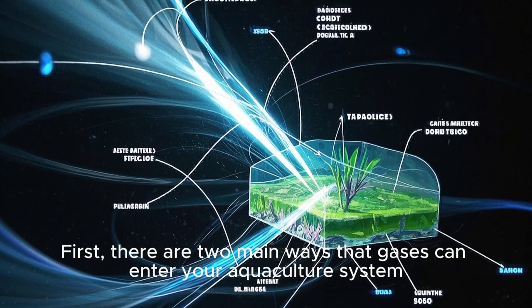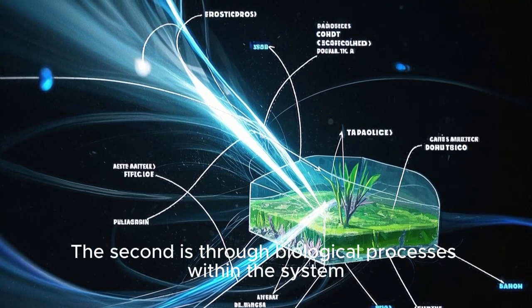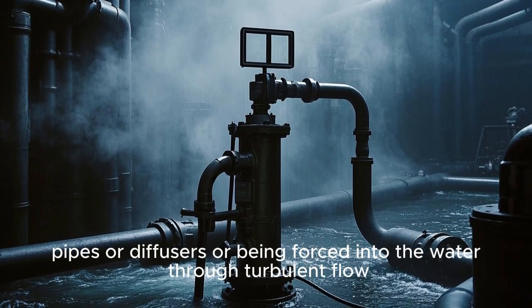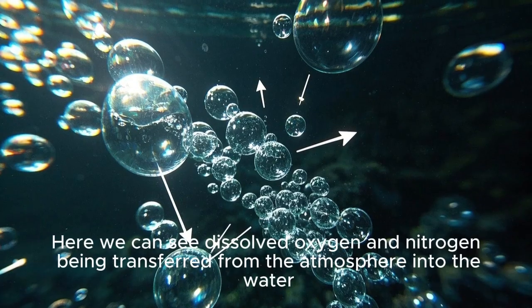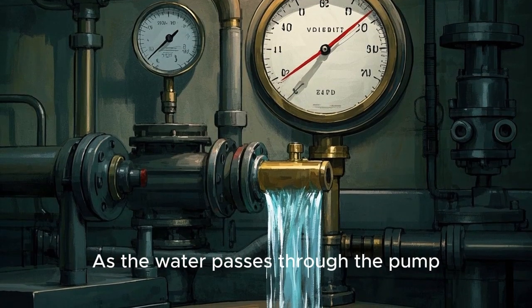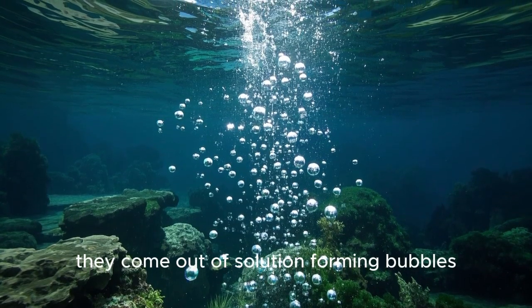First, there are two main ways that gases can enter your aquaculture system. The first is through direct atmospheric entrainment. The second is through biological processes within the system. Atmospheric entrainment refers to air being drawn into pumps, pipes, or diffusers or being forced into the water through turbulent flow. Here we can see dissolved oxygen and nitrogen being transferred from the atmosphere into the water. As the water passes through the pump, pressure is reduced, which lowers the solubility of these gases. As a result, they come out of solution forming bubbles.